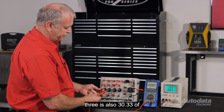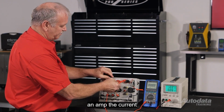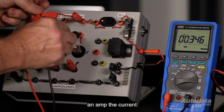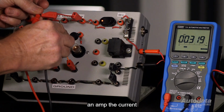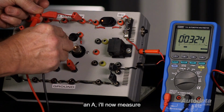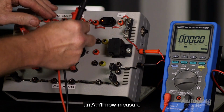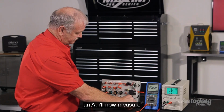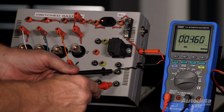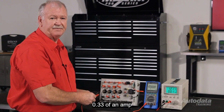Globe 3 is also 0.33 of an amp. The current at globe 4 is 0.33 of an amp. I'll now measure the total circuit current. And again, I've got 0.33 of an amp.